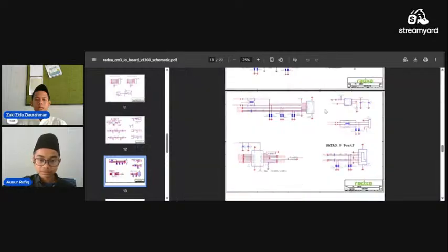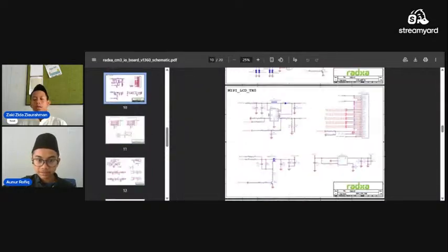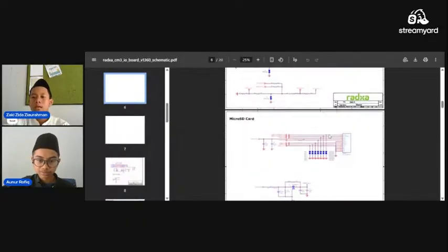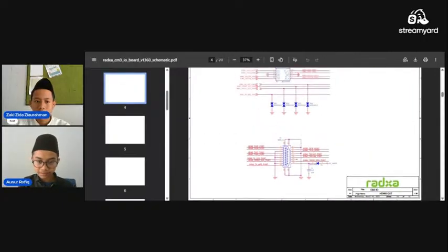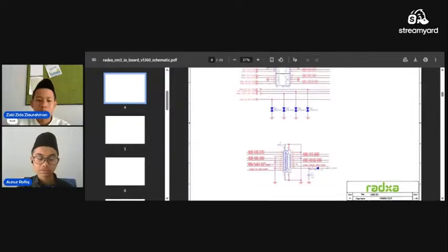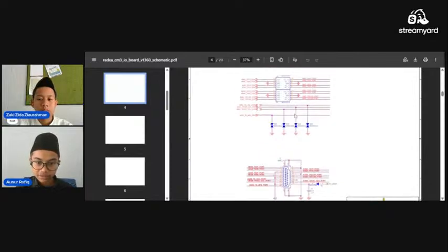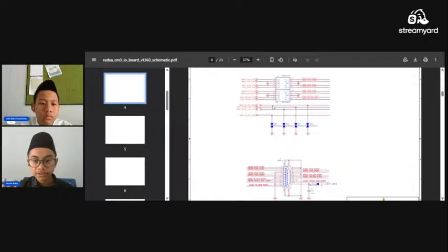Then I will show the HDMI. That's the screen output. Why is this ARM chip so good? Not really that good, but it's good for someone who designs their first board. This chip can do HDMI 4K 60 FPS. As you can see here, we have the ESD protection for the transmitter, and also I2C communication there.